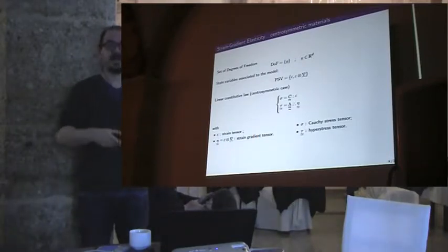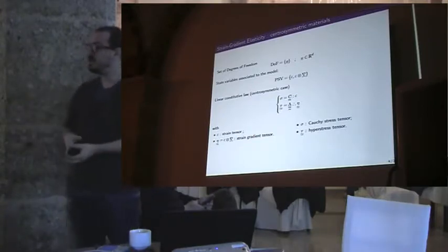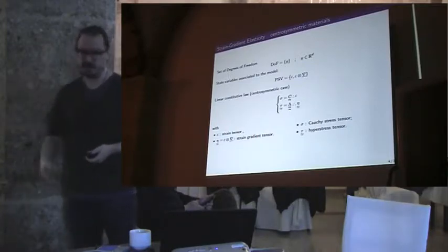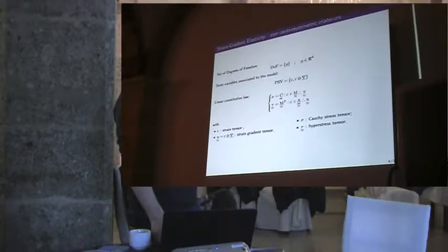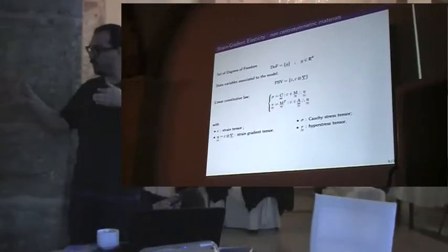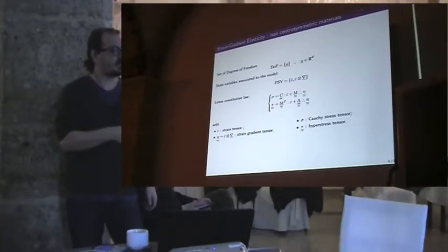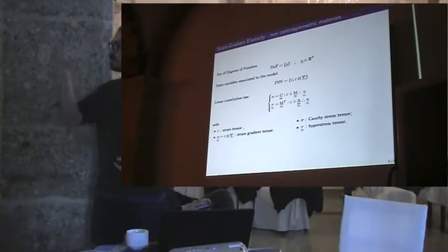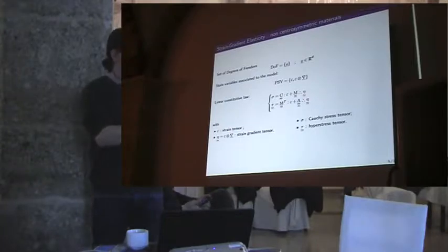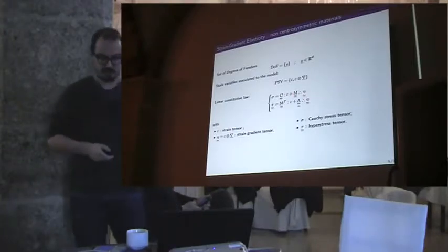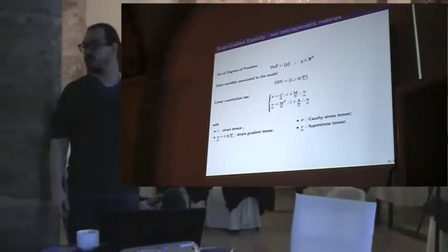Here, the setting is the classical setting studied by people making the assumption that the material is centrally symmetric. If we quit this hypothesis, we obtain the full constitutive law, in which a new fifth-order tensor appears that makes the coupling between the strain gradient inside the material and the Cauchy stress tensor. Usually this coupling tensor is not studied.